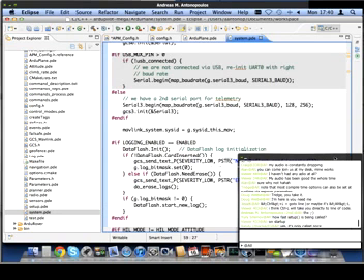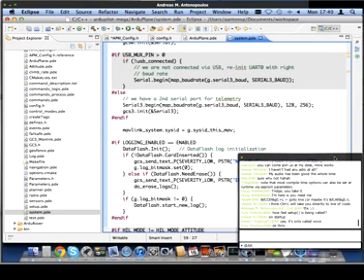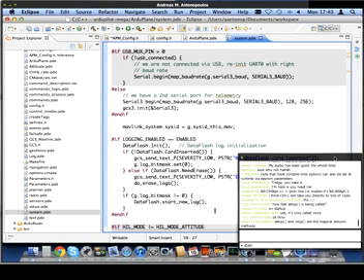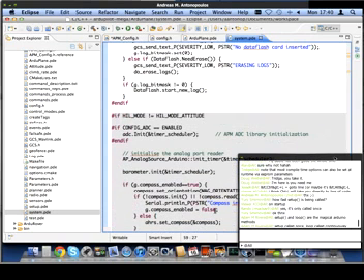The first one is used for the console, which is either the USB port, or on an APM2 it can be mapped to the radio telemetry port. Then we use one for the GPS, and one for a second telemetry port, and then one is used on the APM2 in SPI mode to talk on the SPI bus. So there are 4 UARTs.